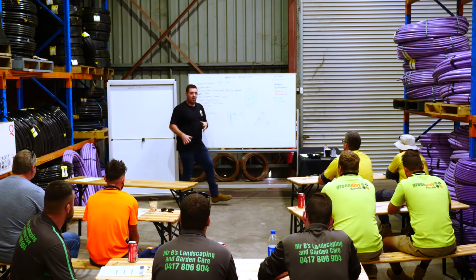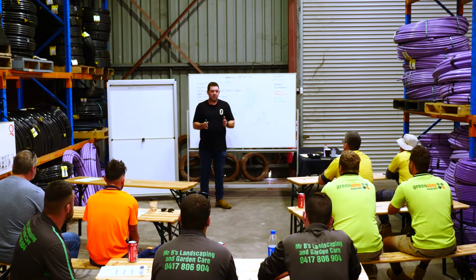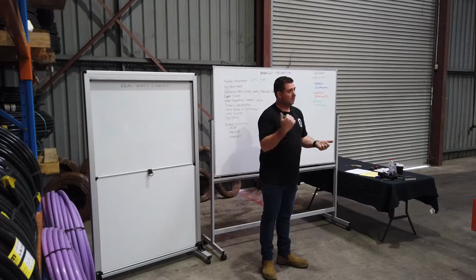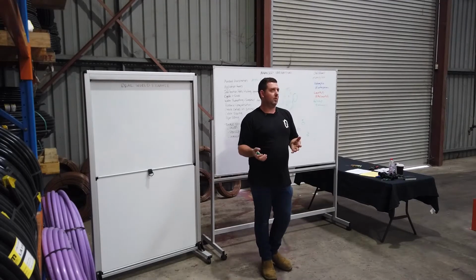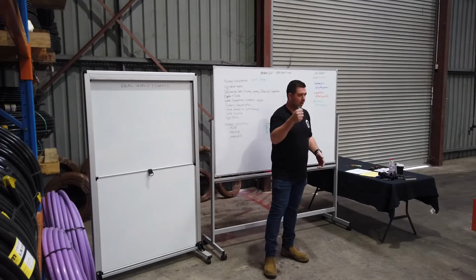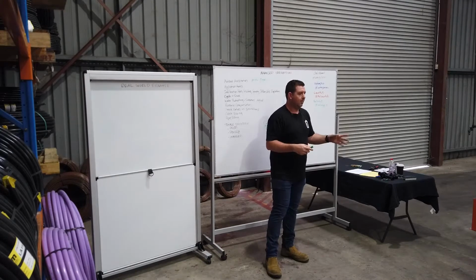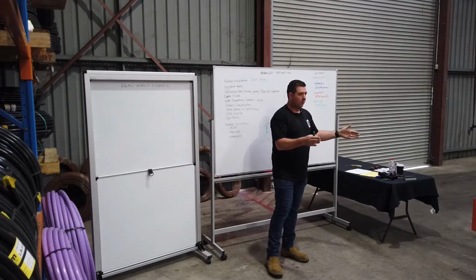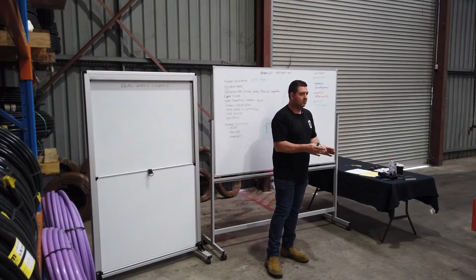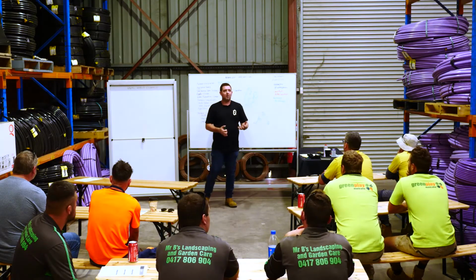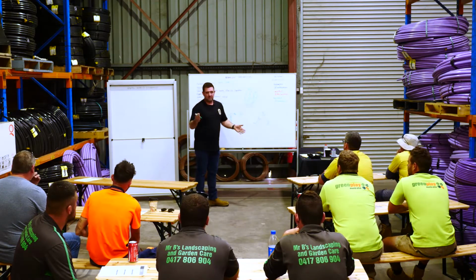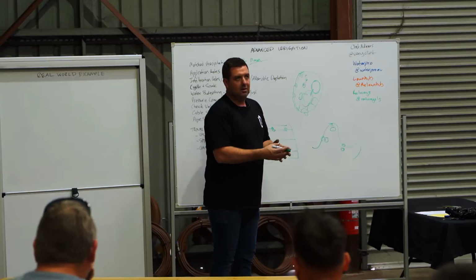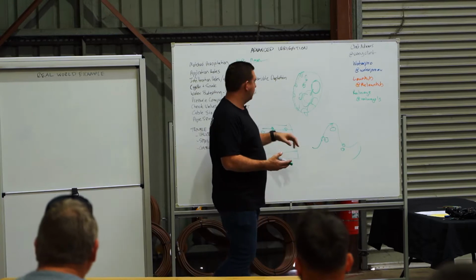So it's not something that I would ever recommend, but if you ever got stuck and you had to run your garden and your lawn on the same line, if you're in a situation where there's already a concrete path there and you've only got one line and the client's happy to move with it, an MP with a 0.4, 0.4, 1.6 is probably as close as you're going to get. It's obviously not a good situation that you're watering your lawn every time you're watering your garden, because they have different demands, but it might be one of those close enough is good enough situations.